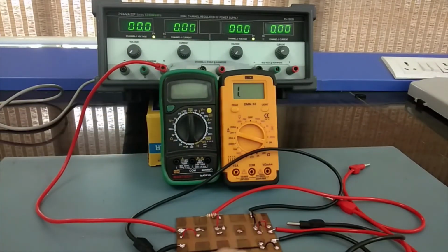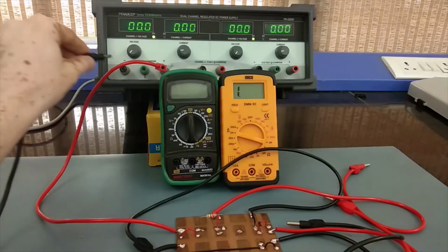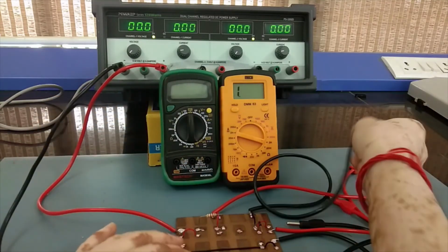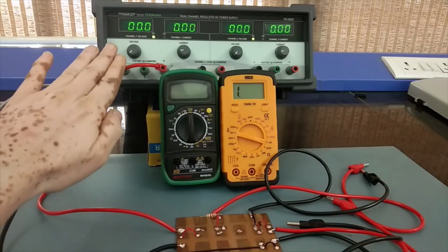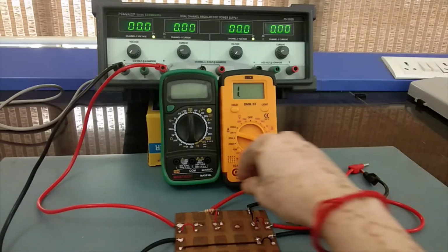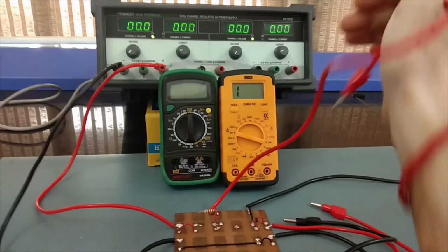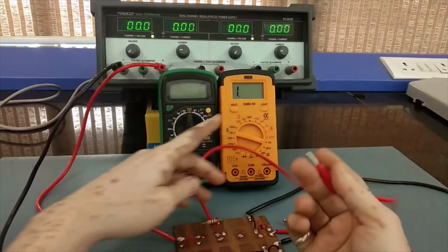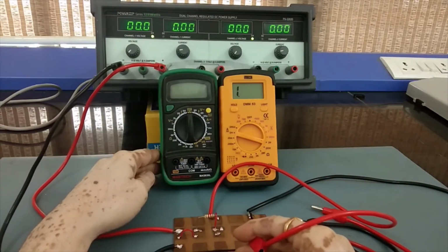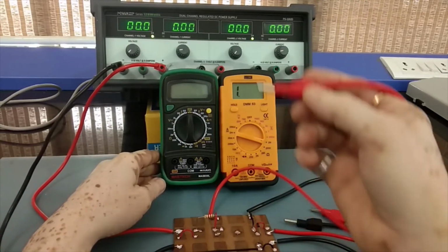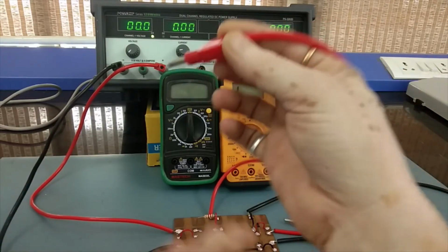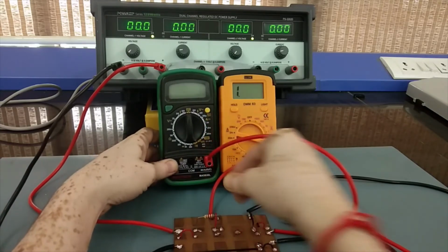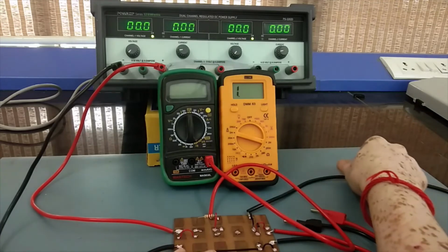Alright. The common ground of the circuit is being connected to the negative terminal, and that's it. That's all from the power supply side. Now we are feeding power to the diode, but this supply cannot reach the diode unless we connect the ammeter. Now you see here, when you are connecting the ammeter, be very sure about the polarity. So this is coming from the positive side, that's why it is red, and you connect it to the positive terminal of your multimeter. Okay, you do not commit a mistake here.